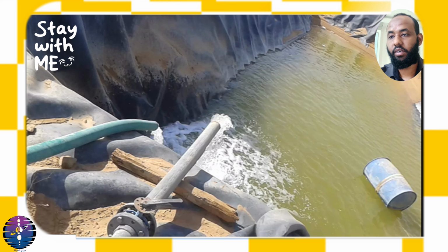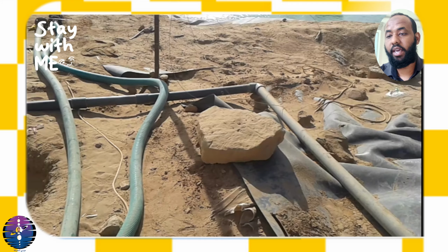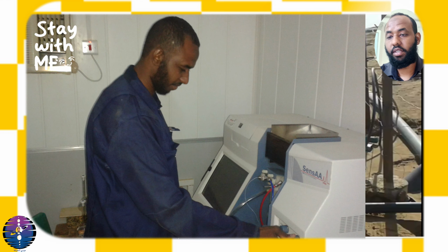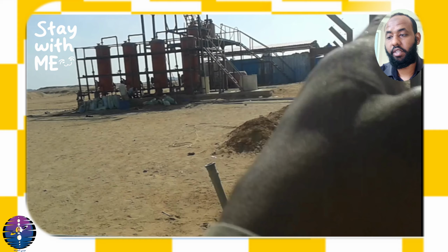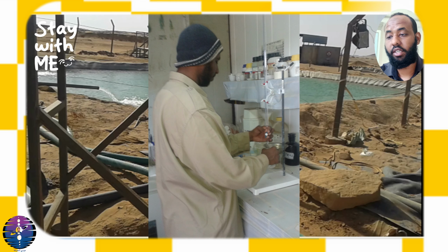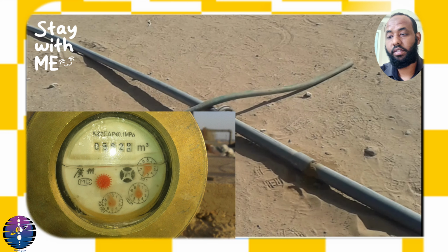into the absorption columns. We take samples from the original pond every 8 hours, for example, to measure the gold concentration using the atomic absorption device. We also calculate the cyanide concentration in the pond through a titration process in the lab, and we read the pH levels.